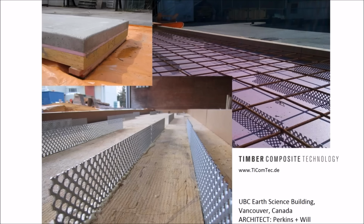There are different ways to create the composite action. Here are some pictures of a project up in Vancouver where they used perforated steel plates epoxied into the CLT and then created almost a continuous shear key between the CLT and the concrete that would be poured in place on site on top of this insulation layer.